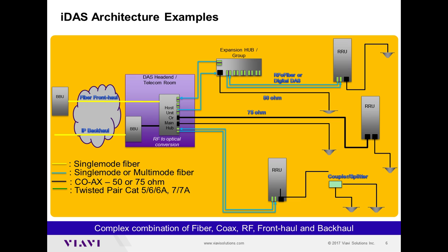Okay, so now let's look at a typical DAS architecture. Like I said, there are two types of DASs. First of all, let's separate them: active DAS and passive DAS. On active DAS, you will see that there is a lot of work going on at the head end where your RF signal that is coming from maybe one service provider or multiple service providers is getting down converted, meaning the signal strength is much more significant.